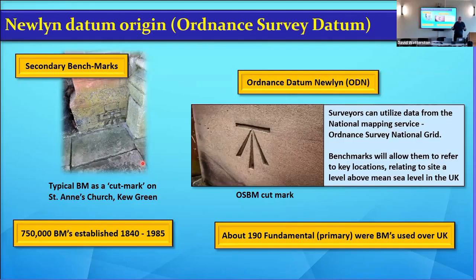So they were using very precise instruments that are down to 1/10 of a second of arc. And they had heliographs, which were mirrors that you looked at the sun, you reflected it, and the guy on a hill 20 miles away could see you flashing. And he knew that's where the survey point was, and he could turn his angle to that and take a shot. So they did multiple rounds of angles, 10, 20, 30 rounds, and then they would mean that all down, and they'll get an angle from point A trig pillar to point B trig pillar to point C trig pillar to point D.